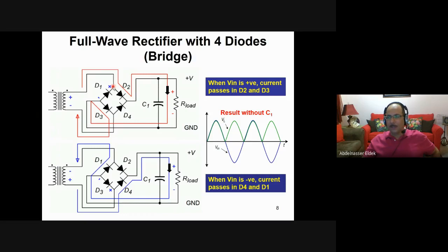At this node, of course, this voltage is positive. Then in this case, this one will be forward bias. The current moving in this direction will not move in this direction because it's open circuit. Then in this case, this one will be a short circuit. Then the current is moving in this direction. And here it will not go in this direction because it's also open circuit. So these two are open circuit now. So it will go through this diode D2 and then continue in the resistor and the capacitor. Continue like this, and then we'll go back to close the circuit like this.